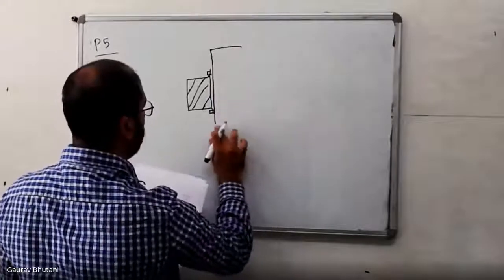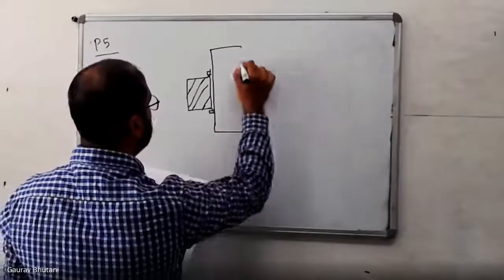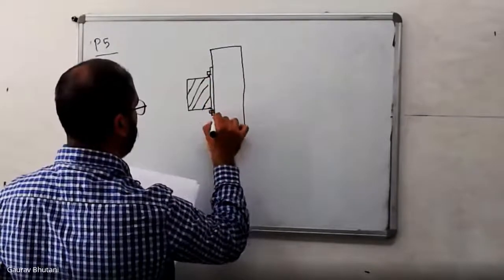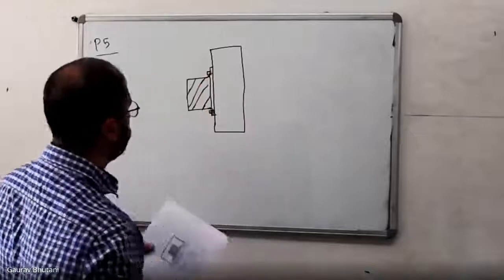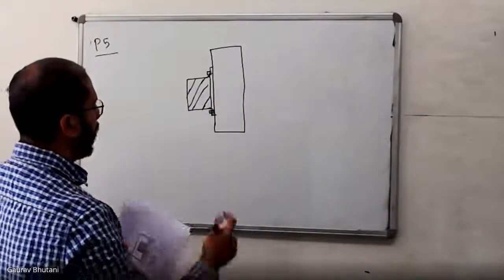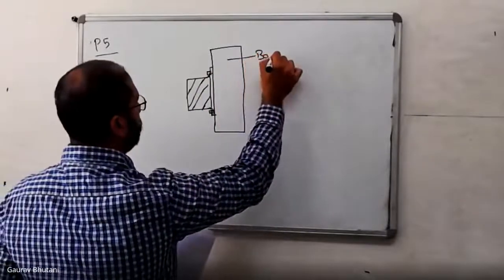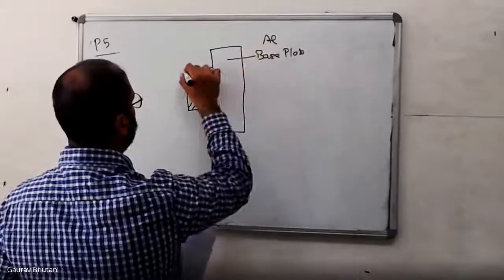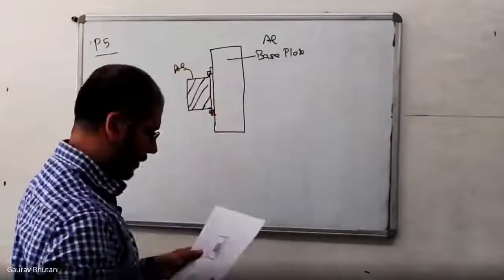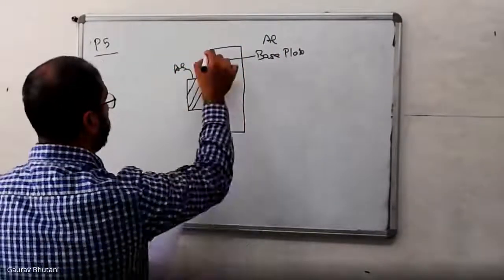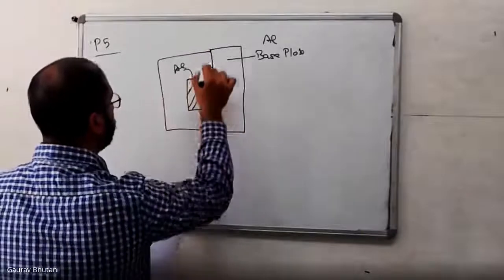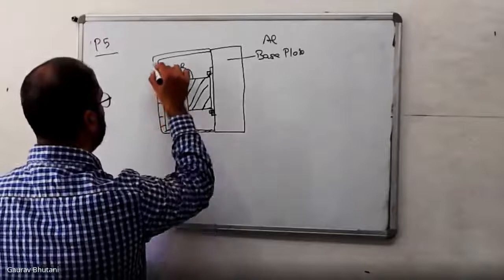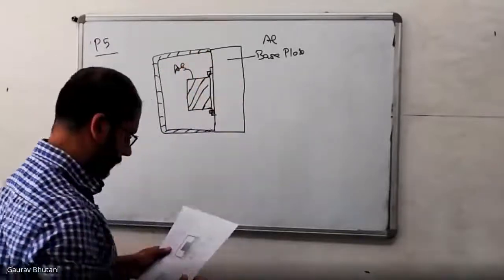Just to give it more area to lose heat, because it's a power transistor, it's supposed to generate heat. Okay, so you have a base plate here. It's aluminium, and this is the aluminium casing on the power transistor. And this again is enclosed in a completely insulating enclosure.